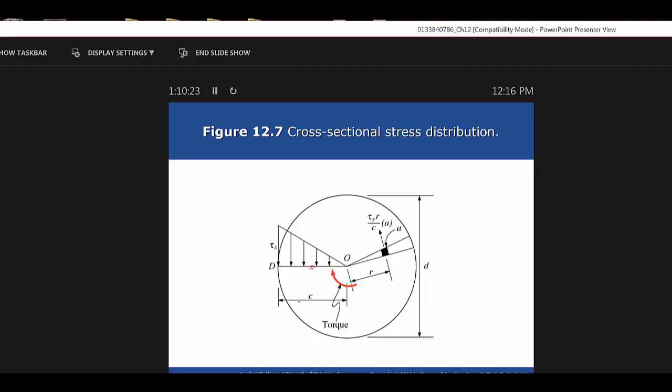If you were given that on a test, you would still have to do that, and that would be one I would probably not look the other way on. So for that shaft, the next increment up would be a 110 millimeter shaft, and you would want to go up, but you wouldn't want to go down if it was 105. Because you'd screw up your shear, wouldn't you? You wouldn't be meeting that value.